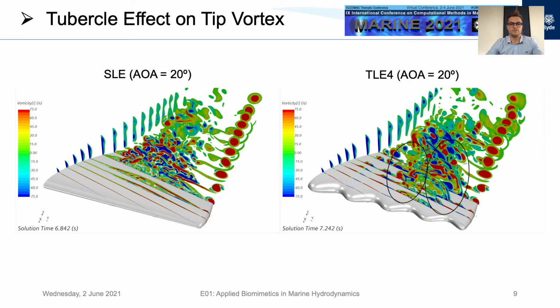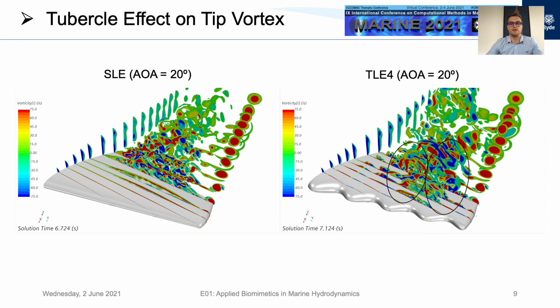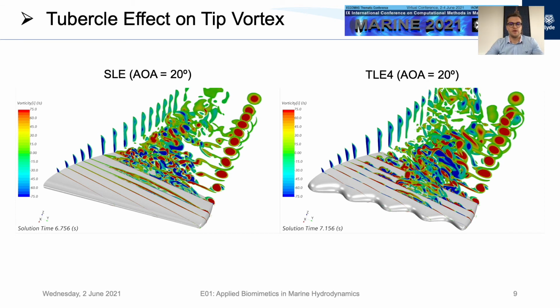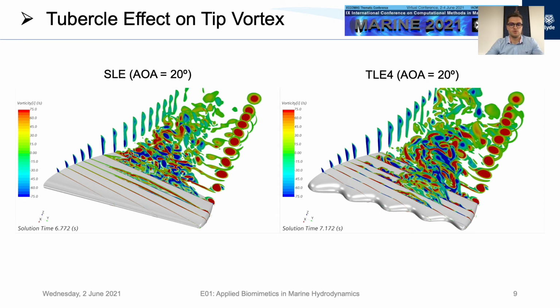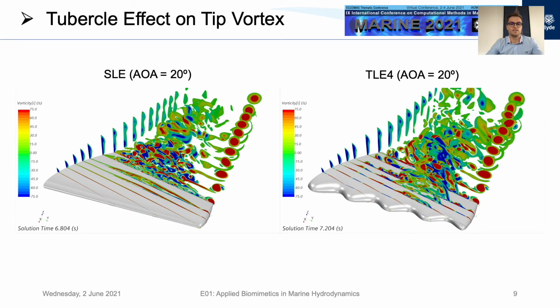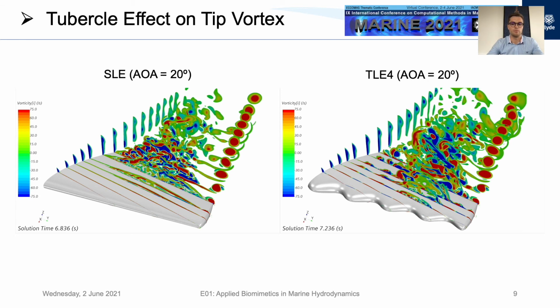Strong counter-rotating vortical elements form on either side of the stall cell, which are initiated by the tubercle vorticity. There is interaction between these vortical elements and the tip vortex, which causes first long-wave instabilities in the vortex path. The tip vortex also appears to be weakened in core strength, but has an increase in circulation, which hints at possible diffusion.